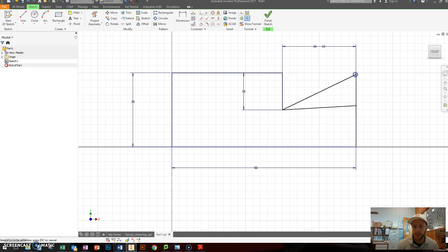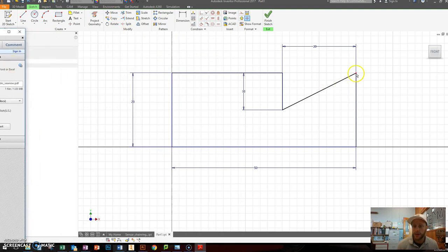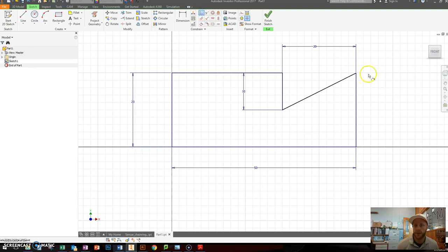And at the moment, at any point in time you can click on your sketch and drag it. So you can click an endpoint or the line. If it allows you to drag it, that means that it's missing some information. So at the moment, this doesn't know the angle of this line here. Now, I'm just going to assume that that point is along the same line as this. So I can put in a constraint here. This one is called Coincident. And what I can say for that one is that that point is on that line. What that does is join together, or just say that that point there runs on that line there. Okay, on your screen that should now turn all purple. When your sketch is purple, it means that it is constrained. In other words, it has all the information it needs.